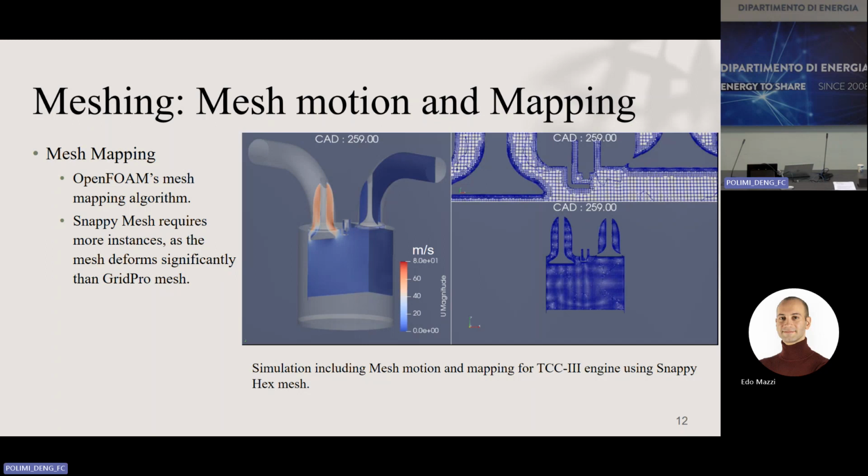So your objective was to resolve the boundary layers. So no wall function, you resolve the boundary layers. No, this one has a wall function. Why did you want to achieve this high resolution with the wall function? Well, in the case of the hex mesh, to capture this, when the valve is just open, I need to have at least 4 levels of refinement just to capture it.